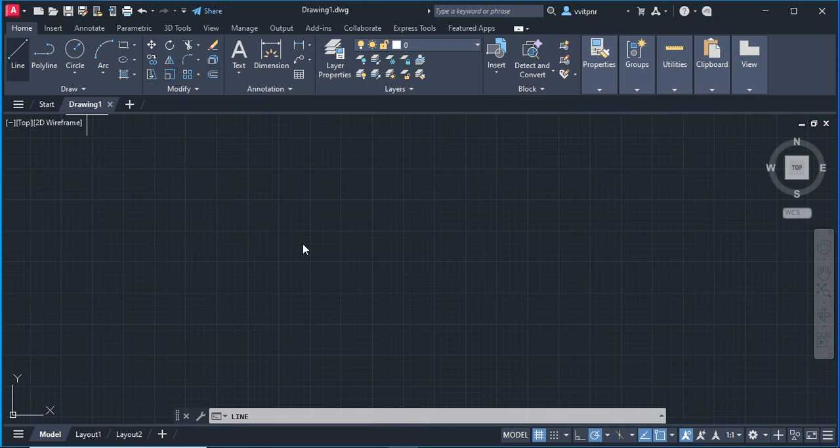You can see on the screen, since the line option is activated, it is asking for the first point and second point. Whenever we want to move to the next parameter, press the Tab button. Tab is to shift from one parameter to another. It was showing the x coordinate first, later we can see the y coordinate. Now I'm exiting by clicking the Escape button on the keyboard. Escape exits the respective command.